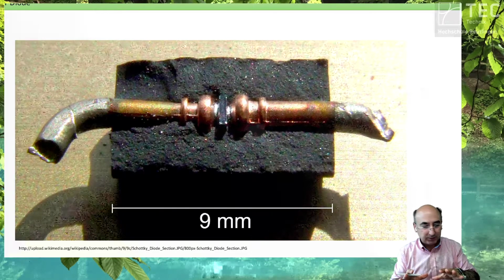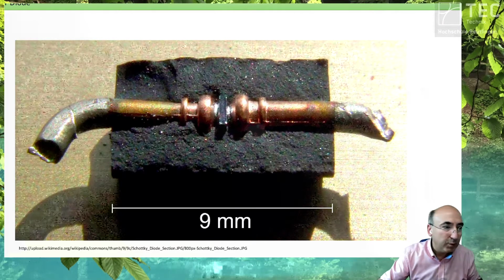In short words, how you produce this. You have a wafer. On the wafer, at the surface, you put on a liquid which consists of the p-doping materials. You flip the wafer. The other side gets the n-type doping material. And then you put these wafers into a quartz glass wagon, close it, and put it into an oven. What happens with these dopants from the surface? They diffuse into the silicon.